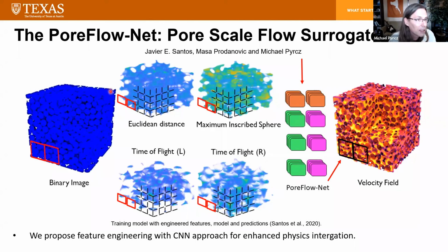We trained a convolutional neural net. We're using a ResUnet type structure, and we trained it to be able to predict the fluid velocity field, orthogonal X and Y, or X, Y, and Z. So we're able to produce the color right here. Yellow is high velocity, red is low velocity. Everybody can see you got that boundary layer close to the grains. The grains have no velocity. That's why they're punched out.